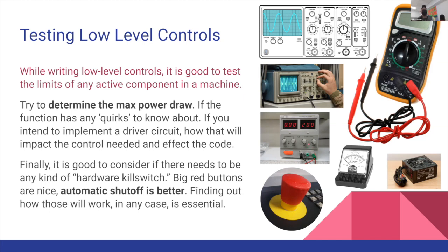It's also important so that you know exactly how to implement a kill switch to make it just turn off. You want to have some sort of a way that you can cut power to the end effector most of the time, so that if something's going awry, you can turn off power. Turning off power to the whole thing is great, but you might also want to be able to press a red button, and even if the whole machine needs to think for a second, you can stop the spinning end mill right now.